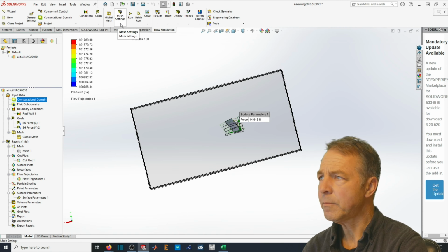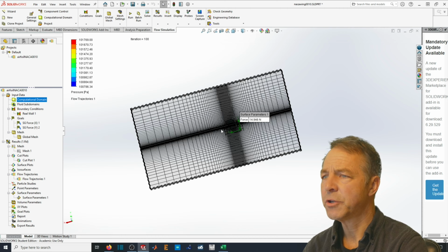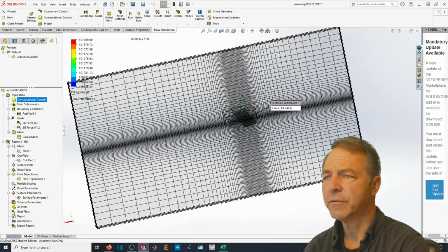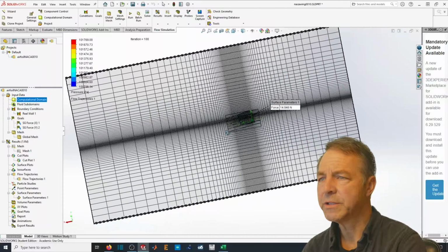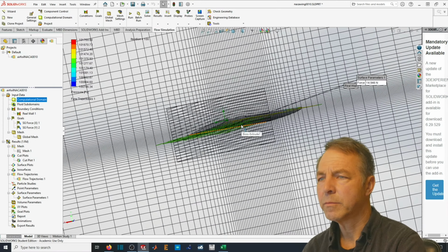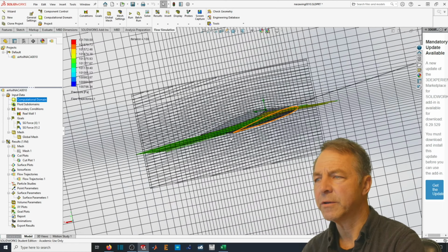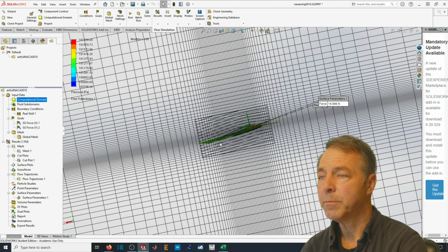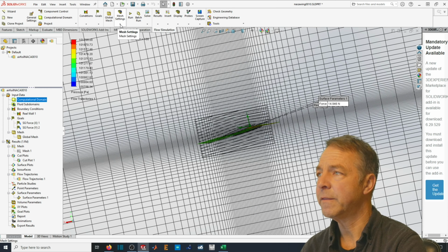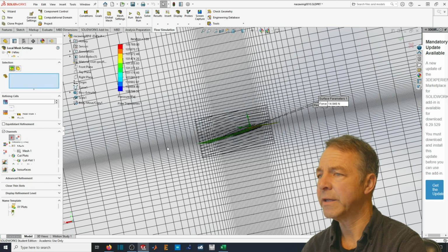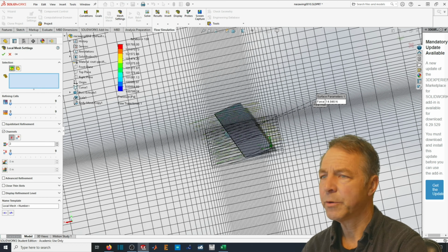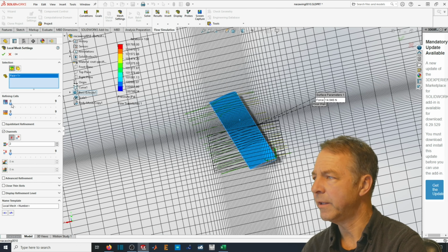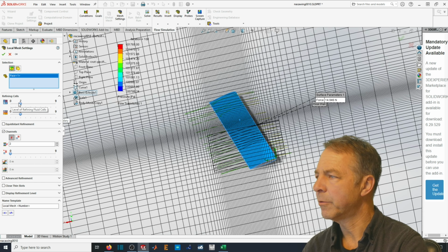And if I go back to show the mesh, you can see that I've refined the mesh as it needs to for the simulation. And I've got relatively fine points in here. Now that I've got so many fewer points, I could actually make some refinement in there. So I'm going to make a local mesh around that body, and I'm going to refine more of the cells.